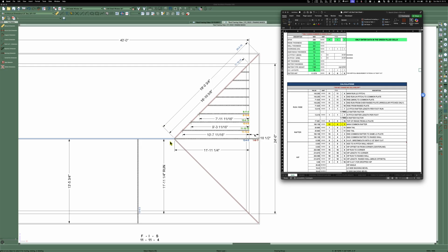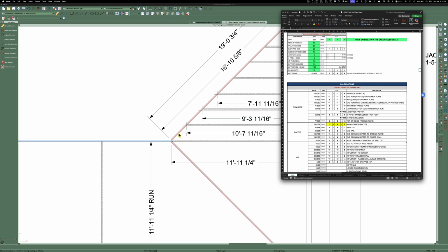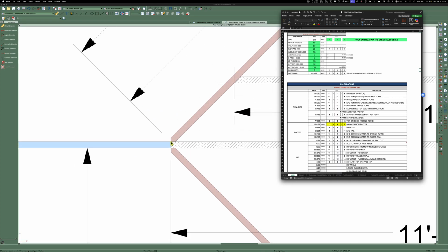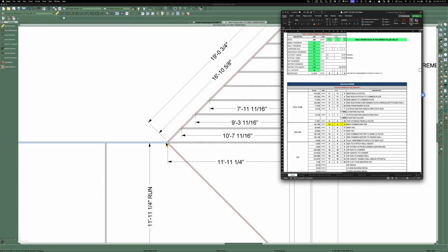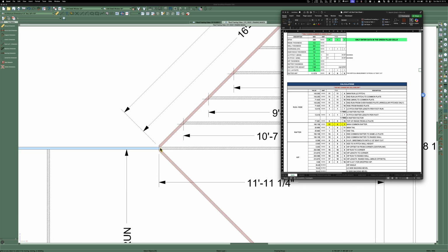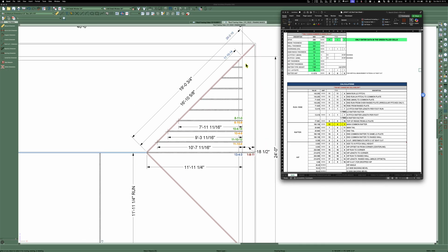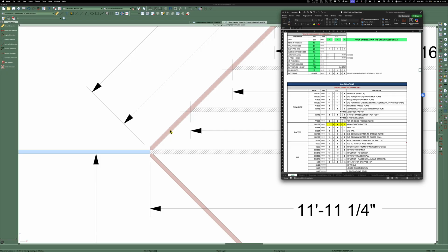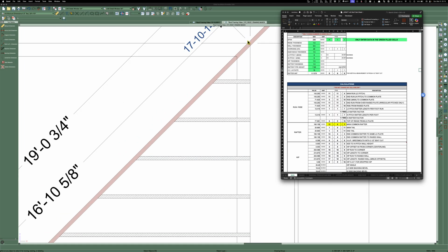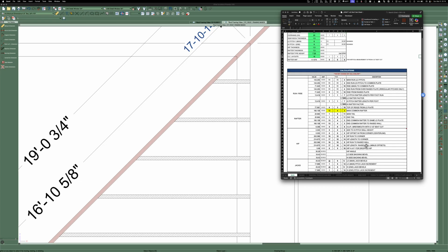So some people just cut the hip and put this diamond plumb cut on. We called it a diamond because it made this point, and then it's a plumb cut. But the super pros, they'll run their saw down both sides of this, and they'll cut the backing bevel on the top of the hip. In that way, that top bevel edge down the middle actually rides right to the top of the ridge right there. If you don't do that, you have to drop the hip a little bit. And then the other thing is you have to cut the bottom the same amount so that the whole hip drops. And I've got it in here as a calculation.